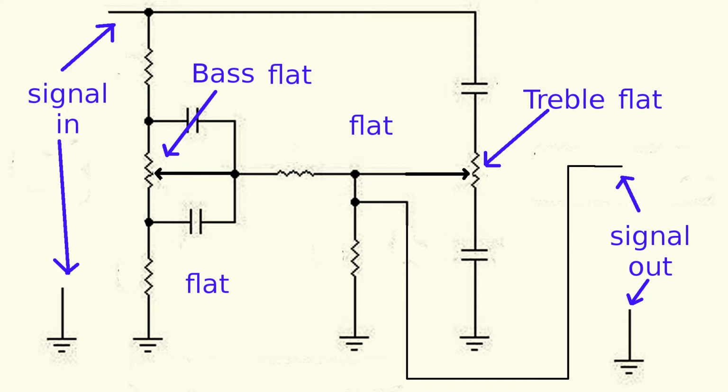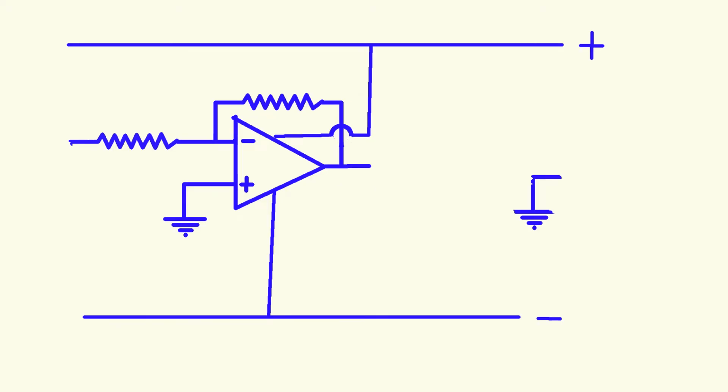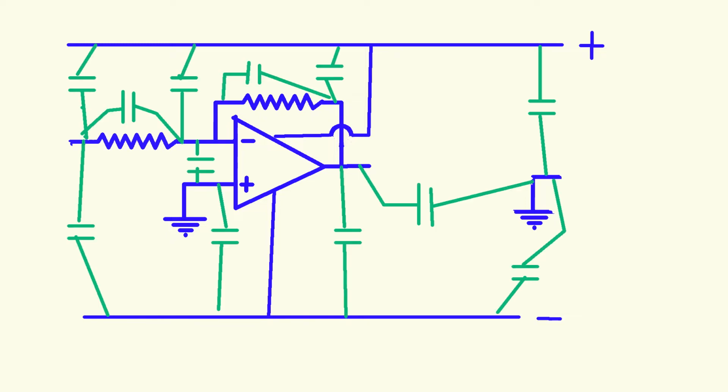A couple more notes for those actually wanting to build something. First, the ground plane. Every pair of wires or circuit traces forms a capacitor. If a circuit is misbehaving, it is usually an unwanted circuit through a capacitance between two conductors.